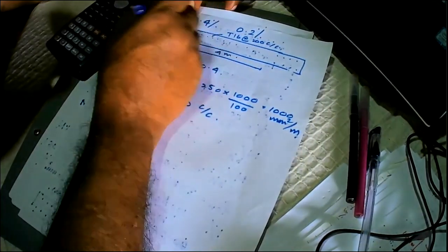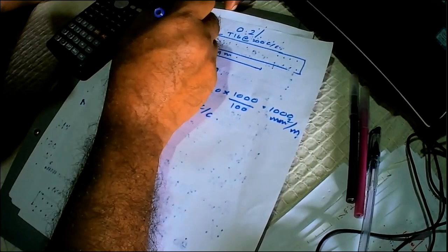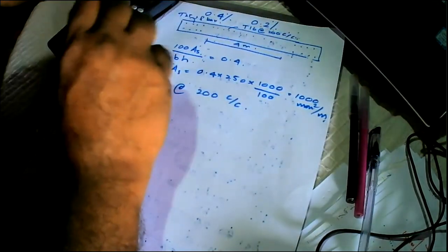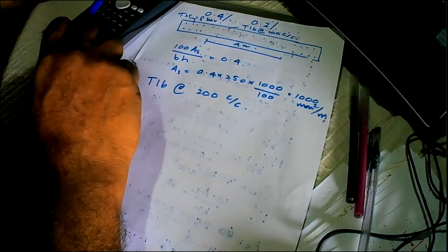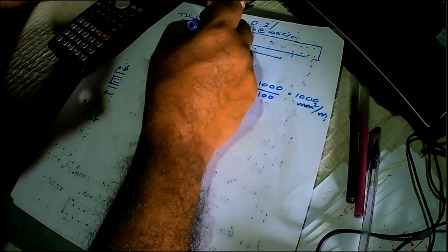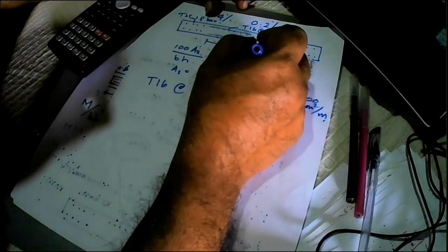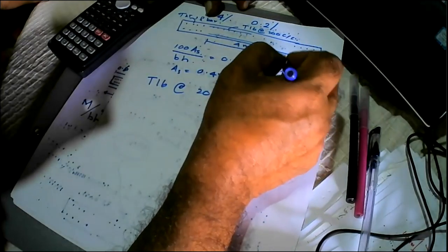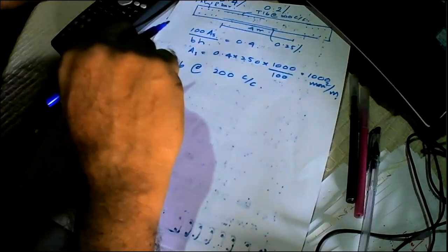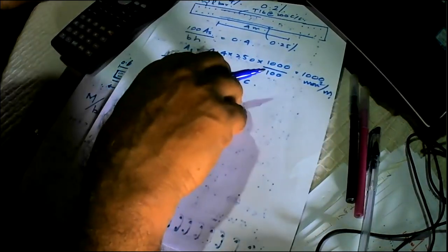And in these areas, we'll have T25, 8 bars in each face. So we can arrange the reinforcement like this. And in the horizontal direction, generally we provide 0.25% reinforcement. 0.25 means, when you add the reinforcement on both faces, you should end up with 0.25.